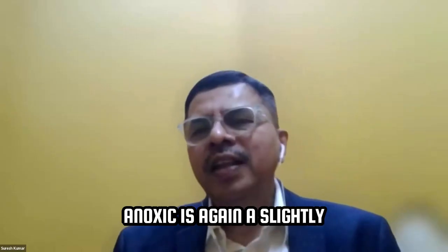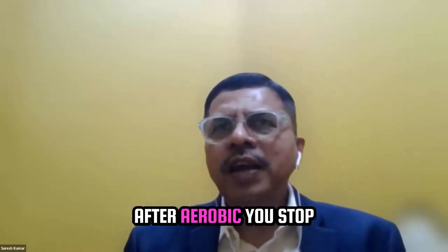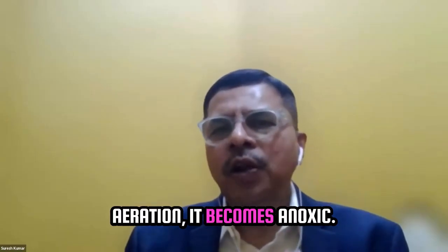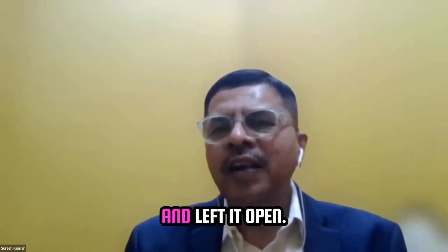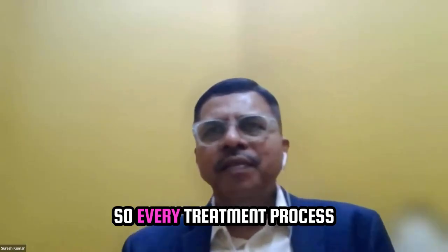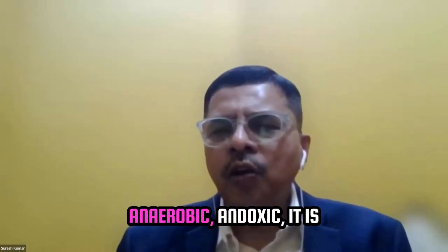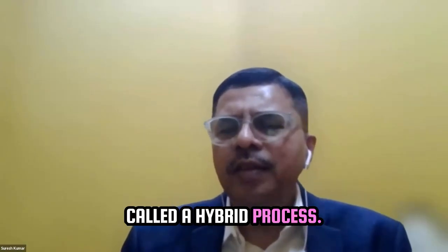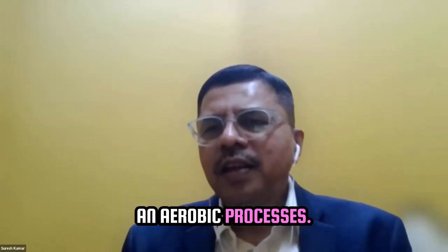Anoxic is again a slightly different version of aerobic. After aerobic, you stop aeration, it becomes anoxic. You are not aerating anymore. You just aerated and left it open. You switched off the blower. Typically, that is anoxic. So every treatment process today, if it uses aerobic, anaerobic, anoxic, it is called a hybrid process. Any aeration processes like MBBR, SBR, they are purely aerobic processes.